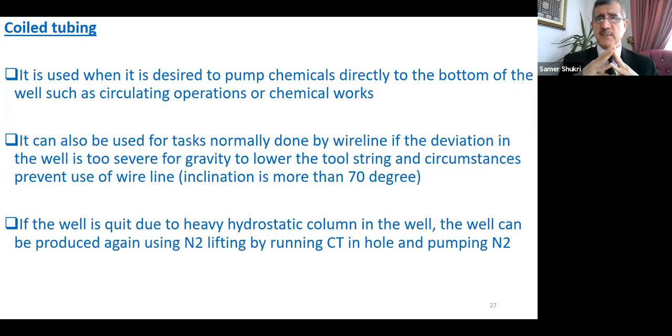It is also used when we want to pump chemicals into the well, from the surface to the reservoir, for example acid or treatment or anything to improve the reservoir productivity. And if there is a skin effect, it can remove the barrier that is formed between the reservoir and the wellbore, and allow the formation fluids to flow from the formation to the wellbore. This is called inflow. Then from the wellbore to the surface, it is called outflow.